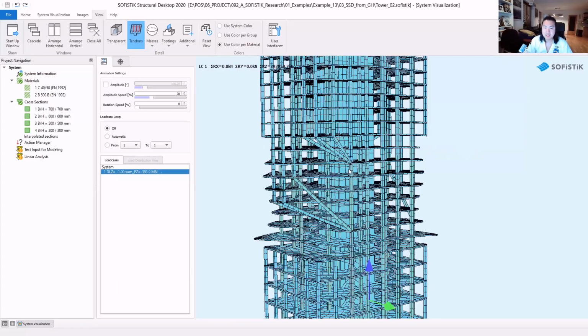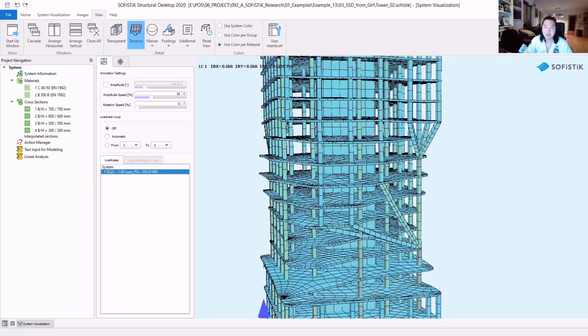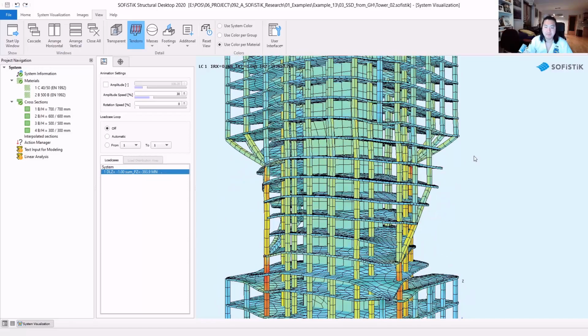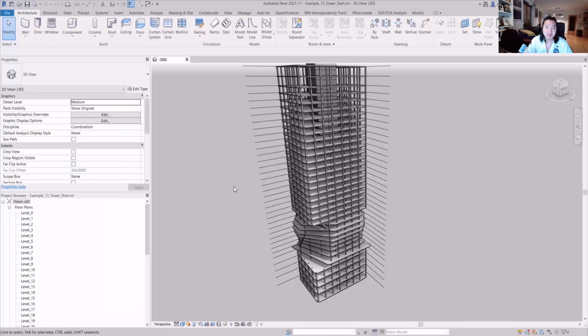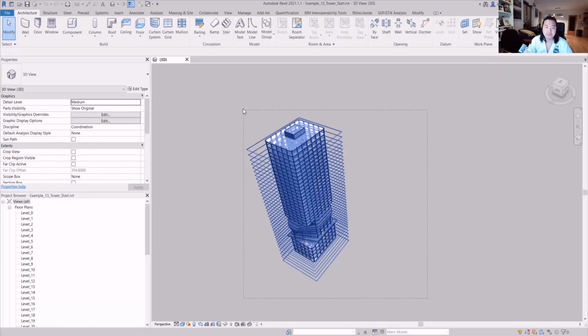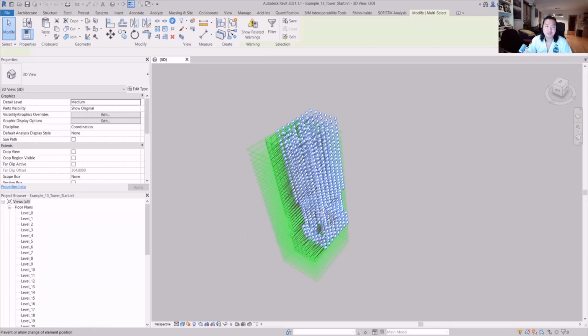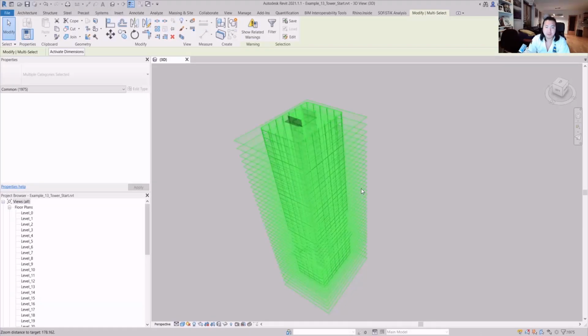And when the structural engineer has approved the concept, then let's say the BIM coordinator or BIM manager who needs to create all this geometry in Revit, we can use RhinoInside script. So back in Revit, let me delete all these levels as well as the elements, so we can completely regenerate the geometry. So first of all, I'm just unpinning the elements.